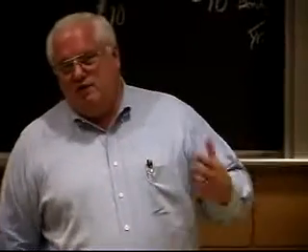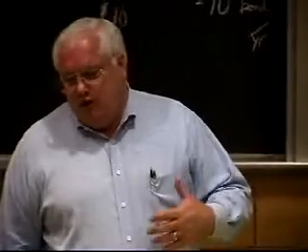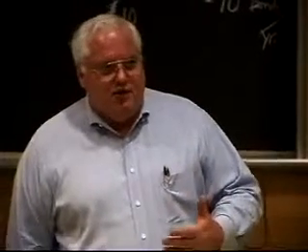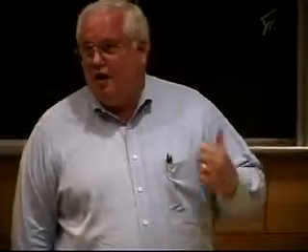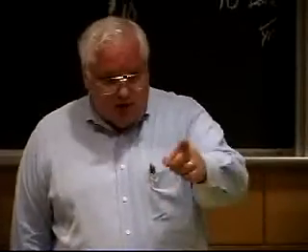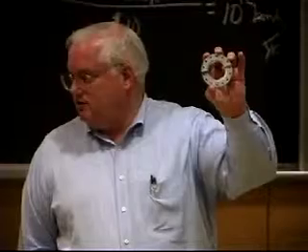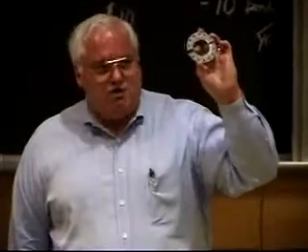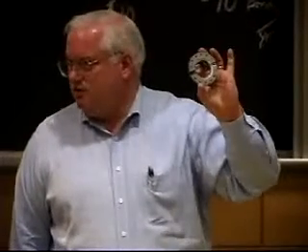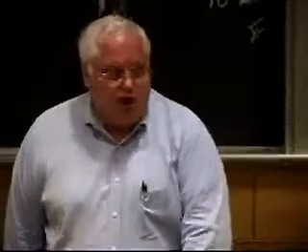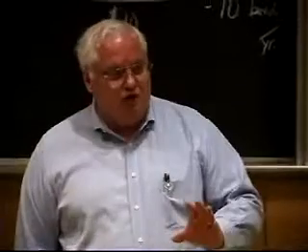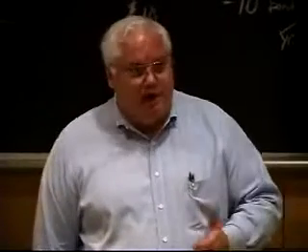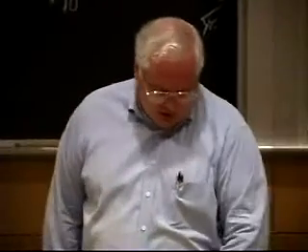I have a student who just graduated and went to work for one of the automotive companies. He just sent me an email. His job is to figure out how to join magnesium because they're trying to save weight. I said, well, don't fusion weld it because you'll always end up with residual stresses. And just like these little washers, magnesium has stress corrosion cracking problems big time and residual stress problems big time. Don't even bother to try to fusion weld magnesium. You can adhesively bond it, and that's about it. You can fusion weld it, but then you have to stress relieve it afterwards. It's not worth the cost.